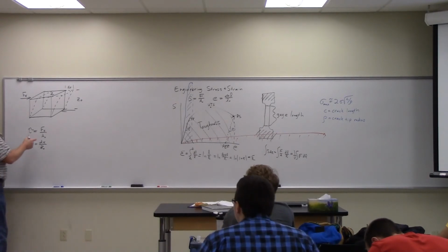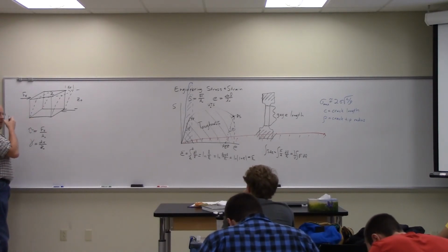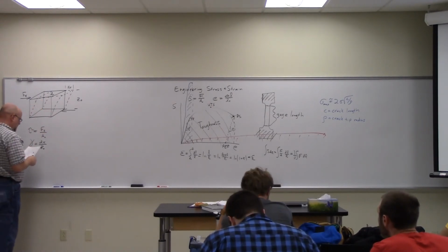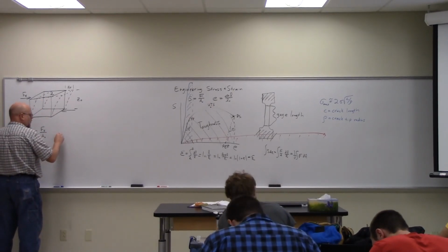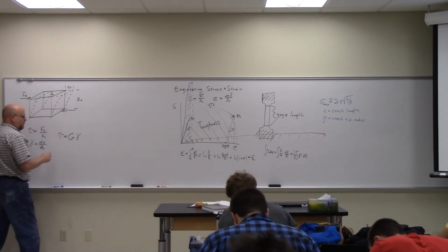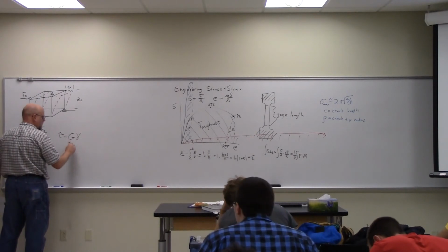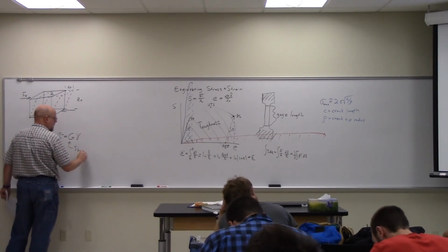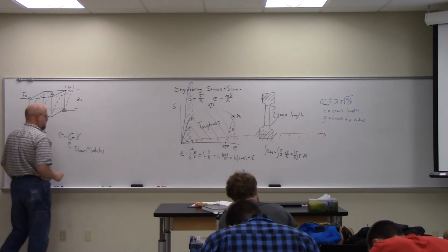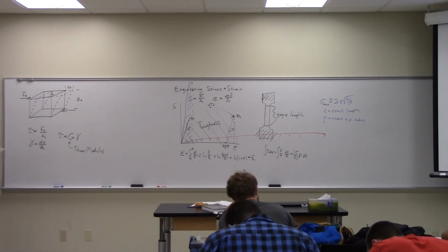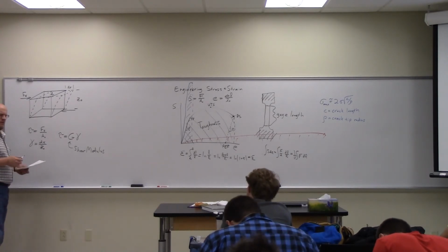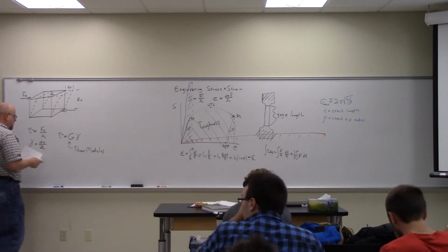So now the dx is still in the direction of motion, or in the direction of force, but now z is perpendicular to that direction. And those two will, in the linear region, be related by a constant which we call the shear modulus, or sometimes called the modulus of rigidity, if that comes up in any of your homework problems.